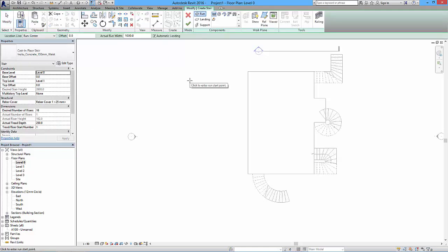And when you load that stair by component tool up, we've got a whole host of different things to look at. So we've got the run, we've got a landing, and we've got a support. These are all component based elements. And then we've got the run, and then the full step spiral, the center end spiral, and then you've got the L-shaped winder and the U-shaped winder. And then we've got a sketch, so we can just basically sketch it in as well.